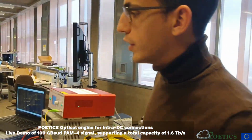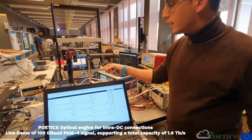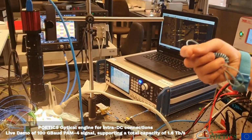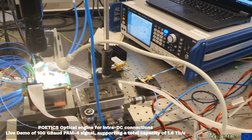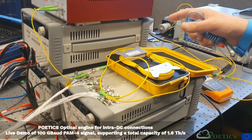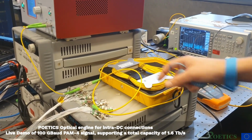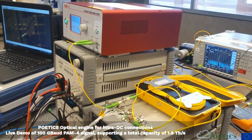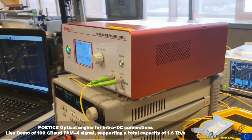Thank you very much, Johan. As Johan explained, the EMLs generate the optical signals on chip, on the optical chip. And then these optical signals get routed through this fiber array through the rest of the optical setup. Firstly, we have a fiber transmission of 1 kilometer length, which you can see here. And then the signal is fed into a fiber amplifier, which amplifies the signal and compensates for the losses.